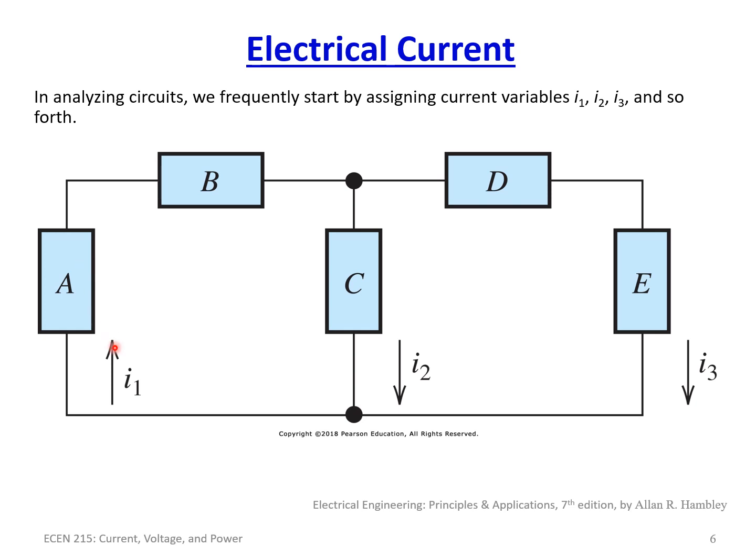The direction of the arrow really determines, and you set the direction of the arrow when you do your circuit analysis. When you work out the equations for this, which we'll be going over later in this class, it's very important that you keep your directions the same based upon the arrow. You could do the circuit analysis and determine that the current flowing through element A is actually minus 5 amps for I1, and so the current's flowing this direction. Sometimes you're going to want to just say the answer is 5 amps. Well, no, it's minus 5 amps based upon the direction that was set. So it's very important you pay attention to the arrow and direction.